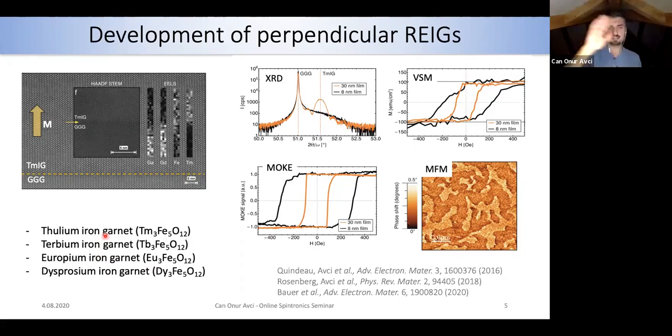But its properties, from a spintronics perspective, are poorer with respect to the other ones. To wrap up, the disadvantage of the garnet films is that you need to start by growing the garnet films and then build your device on top. So you have less flexibility on where you can use your garnet films, and they need to be grown on a specific substrate, epitaxially. And there is also a high temperature involved in the growth, because otherwise you don't get this nice quality if you don't anneal your sample, or if you don't keep the substrate at a high temperature during the growth. So these are the apparent disadvantages for me, but these are all from a materials perspective.